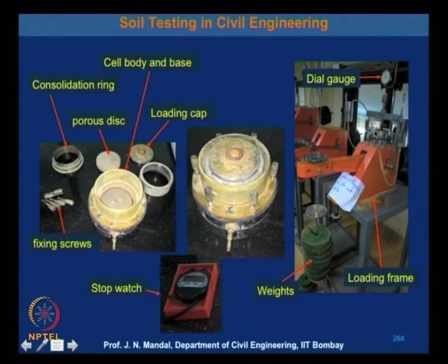Then this is a loading frame, and here load is applied, different weights you have to apply, 1 to 4 kg per centimeter square load, and at a particular time using the stopwatch you read the dial reading and continue for a longer time.